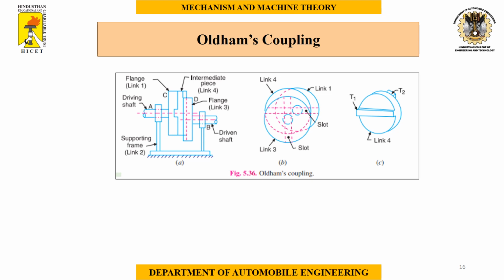The Oldham coupling has two slots similar to plates C and D. Because of this, the Oldham coupling's intermediate plate exactly matches with links C and D, so that the entire rotation of C is converted into rotation of the output member D, which is further used for a very smooth manner of transmission.